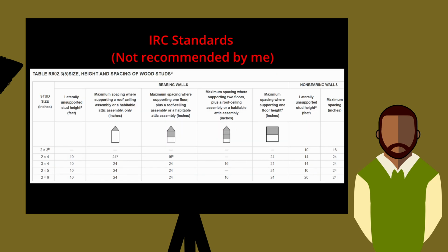But the idea here is, if I had to make a broad statement about 2x4s, and I had a gun to my head, because I definitely like nuance way too much: 2x4 versus 2x6, above 9 feet, you're looking at a 2x6. Below 9 feet, or 9 feet or below, is 2x4. That's where I would usually stand with those things.